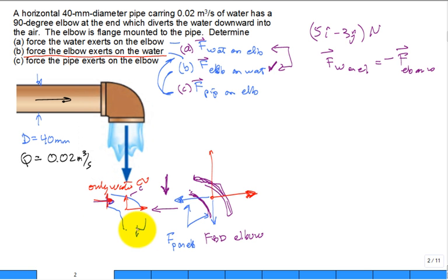Inflow. What do I have across that boundary? Outflow. Do I have a pressure distribution across this boundary? Atmospheric pressure. So essentially we work in gauge because it drops out the atmosphere. But what about the pressure over here on the inlet?